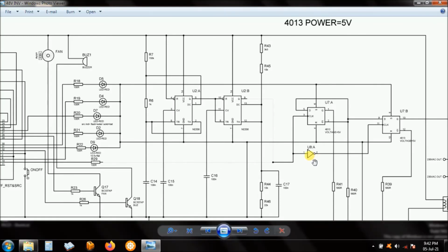You can use a transistor if you want for inverting. Most designs have a transistor there. On my design this is actually using high pulses. It's because I've fixed this charging time to be very short. That capacitor charges quickly, so the high pulse is there for a short time, so you have high pulses there. So my design is having high pulses rather than low pulses.